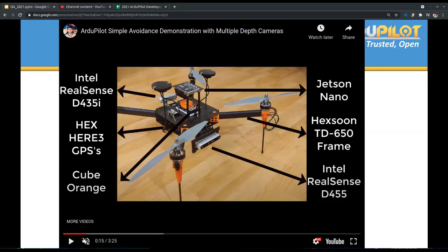It's that easy. But with these 3D cameras, it is important to know that all of the calculations actually happen inside the vehicle, inside the flight controller, and the only usage of the companion computer is to connect to the cameras, extract the depth image, divide it into a 3 by 3 grid, pack it into an XYZ obstacle and send it as a mapping message.